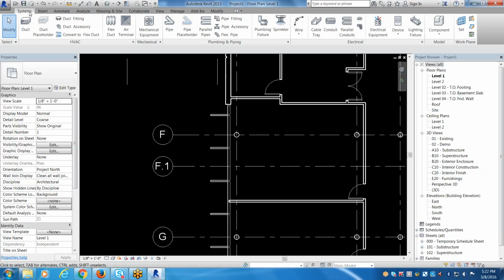Here's where we get into electrical. We'll talk about wires on Friday, conduit, cable trays. Sometimes we model these. It really depends. If we're on a project where we have large conduits that need to get coordinated, 6-inch conduits, 4-inch conduits, we usually will route them. And they work really the same as pipe. And then we get to our light fixtures, electrical devices, switchgear, panelboards, anything like that.